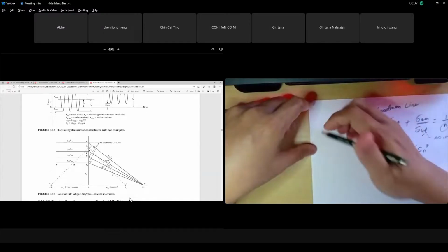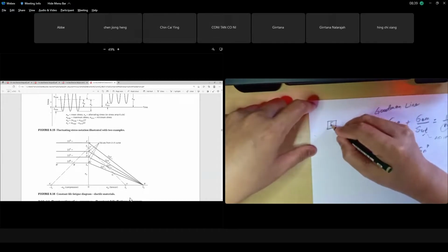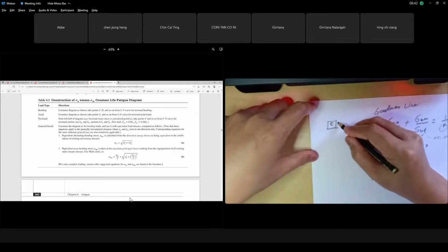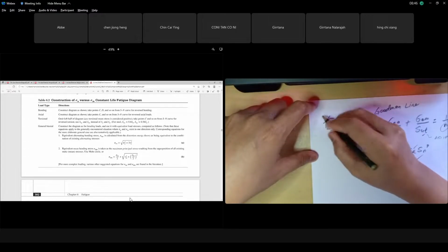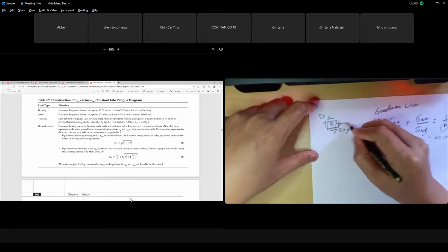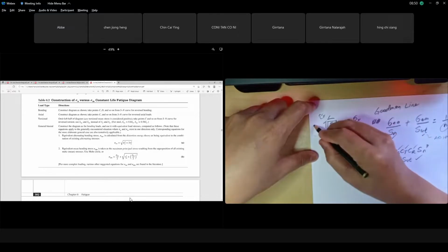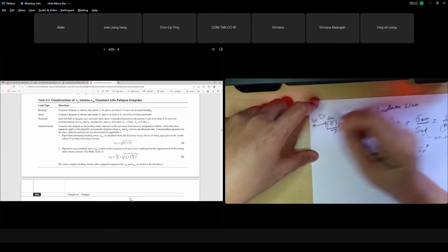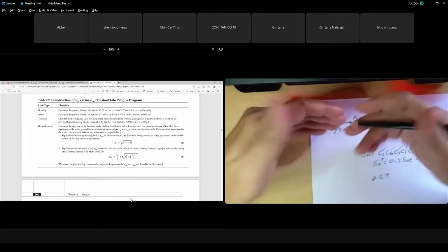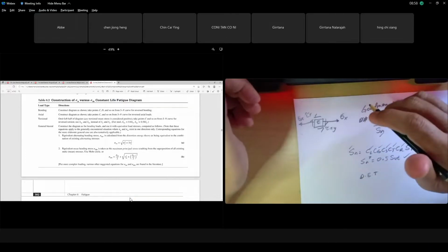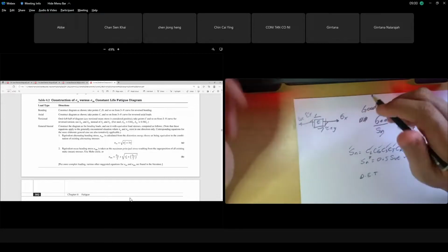Okay. Normally in a shaft element, we always have shear stress tau xy because of the torsion of that shaft, and also we have sigma x. Rarely in a shaft we have sigma y. This is what we call biaxial stress.